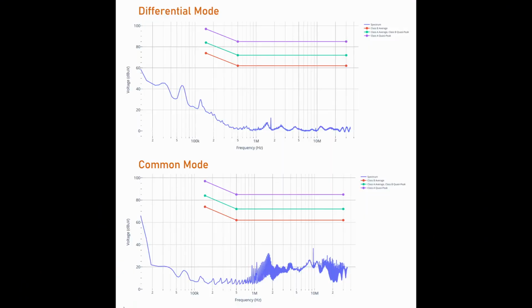Similarly, if the signals are subtracted, i.e. channel 1 minus channel 2, then I see the differential mode noise, which might be coming from DC-DC converters and perhaps of a lower frequency.